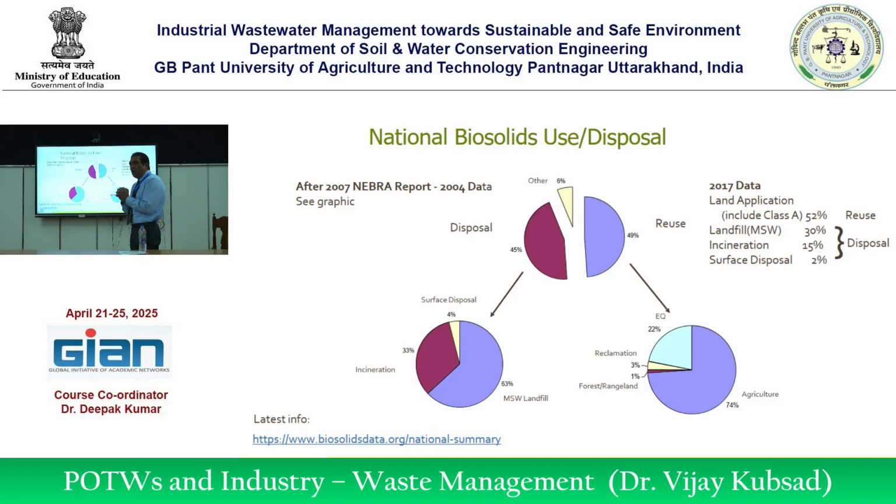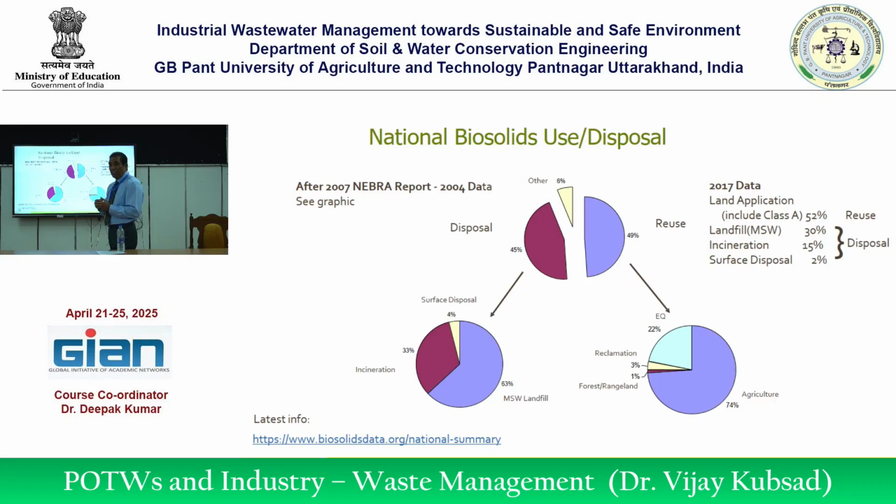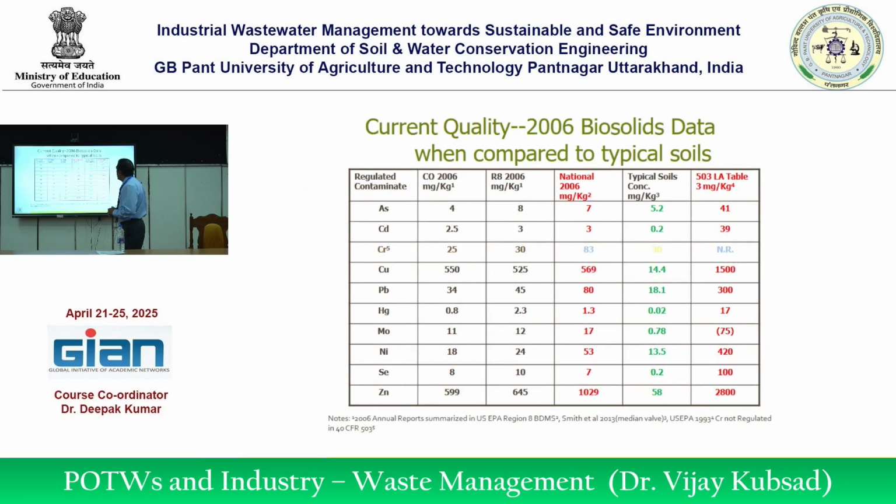There are certain biosolids where, if it is contaminated, what will you do? Then you have to incinerate. That is why yesterday I was telling of wastewater coming from hospitals and clinics. It has to be incinerated, however small it is, right? Or any clinics, everything should be incinerated. If it is contaminated, you don't have another way to treat it. That is why it is so important to prevent toxics from entering the systems.